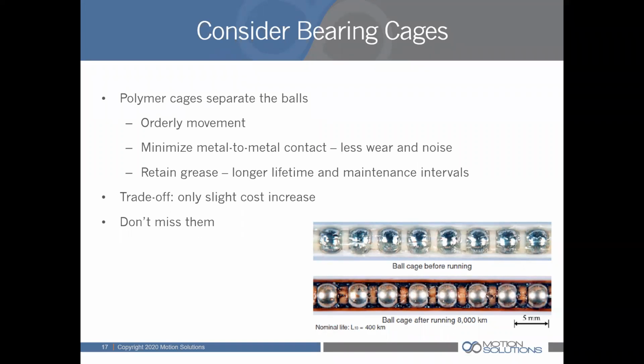I'm just going to give an example. We had a semiconductor application where we designed a vertical actuator that was supported by linear guides with cage ball, with a heavy moment load. We had about 600 pounds sitting about 10 inches off of the front of the bearings. And we also had a cage ball screw. And so we ran a life test. We ran this unit with 600 pounds on it, 24 hours a day for 6 months.